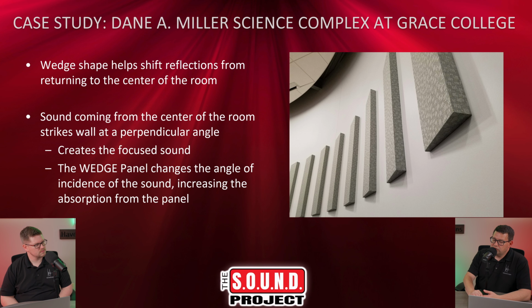So this next photo shows you how that wedge panel looks. You see the thin section, it slopes up to a thicker section, and so the front face is always angled. Now you could do it with flat-faced panels, just normal acoustical panels, but you'd have to mount them on the wall with the angle built in, and that's sometimes hard to do. You've got to do wood blocking and create the angle yourself, whereas the wedge panels do it for you.